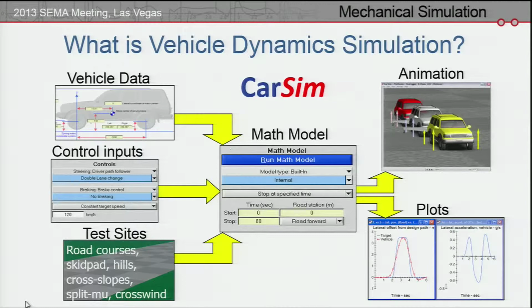There's kind of an interesting aspect about testing in the virtual world, and that is that the vehicle is fully instrumented. If you want to do a test, let's say with a new suspension component, you might want to know what the loads are going to be, say, in a spring hanger bracket. And for those of us who come from industry, we know the effort and expense of building a transducer to measure it. Guess what? In the simulation world, the 400 or so variables that are computed here in this virtual world are there for you to observe.